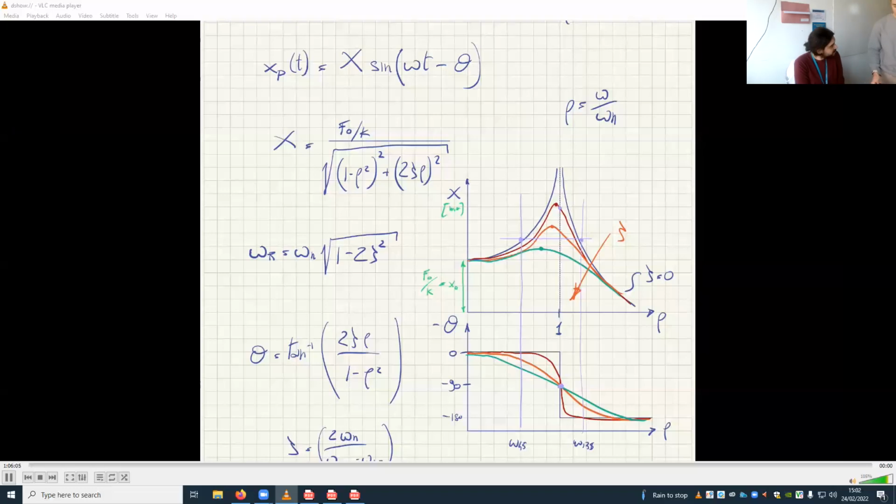No, look at it. First, we don't use the polar moment. That doesn't mean anything. But that would be the internal torque of the shaft. That's not what you're calculating. You're calculating the friction torque between the shaft and the wheel. That is an external torque on the shaft. It's not the internal. That T is the twisting torque on the shaft, which is a completely different thing.